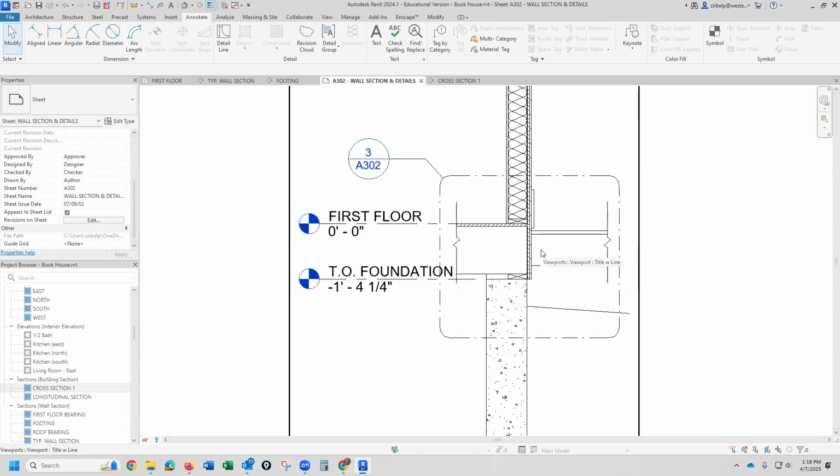Did any of you find any deck collapses when we did our structural failure case study in the last collapse? I don't know if any of you did them, but they're fairly common. They've happened in Winona. They've happened here in La Crosse. I think they happened in Alaska once. And what happens is people have a party and their deck is packed. And then these bolts that hold the deck onto the house, onto the rim joist, rust out, and the whole thing collapses back down against the house.